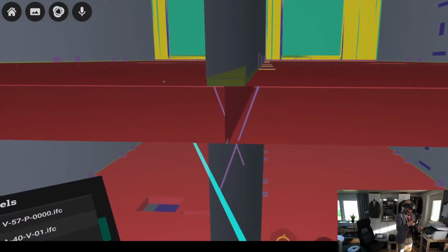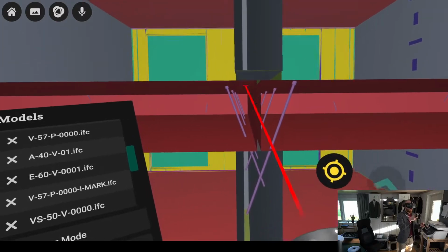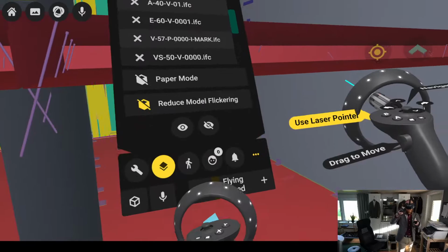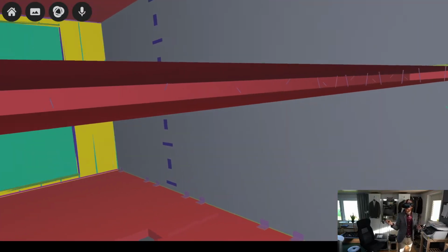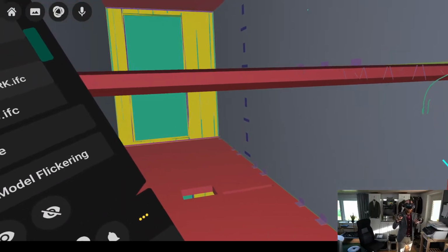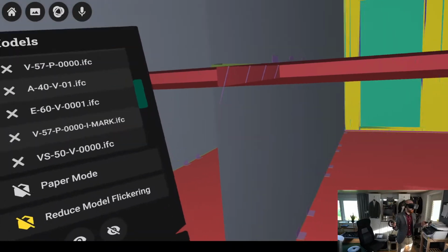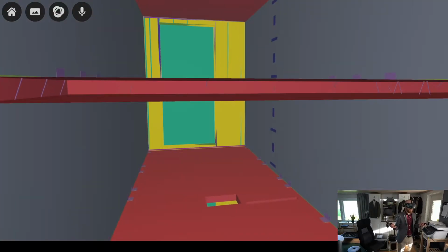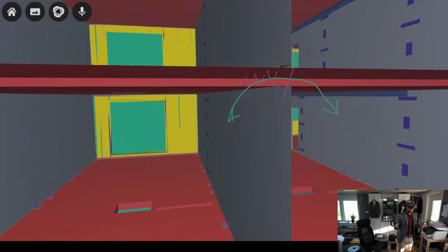And if you have this connection with a slice, it's weaker here, and that can perhaps mean that you will have to increase the thickness of each slab, whereas the continuous slabs can be made somewhat thinner for a given span width. Those are some consequences that you have to take into account, and it's very important to know about.